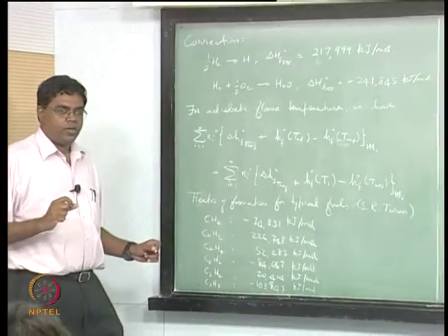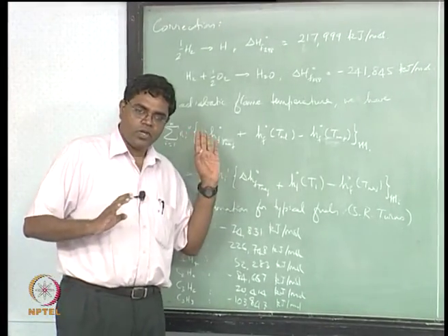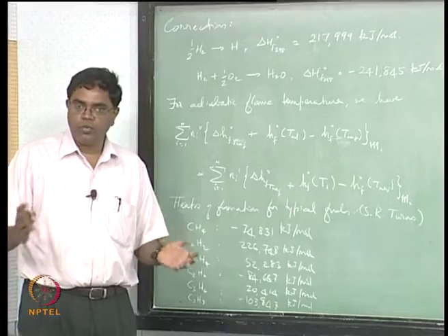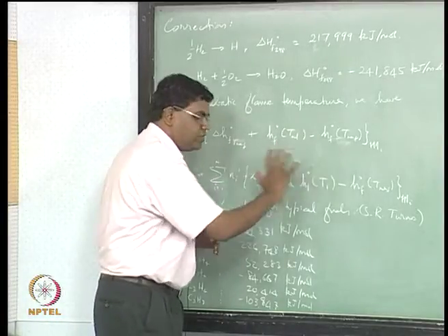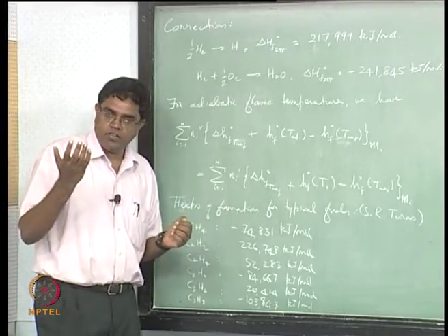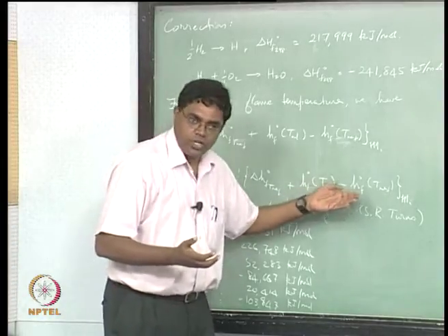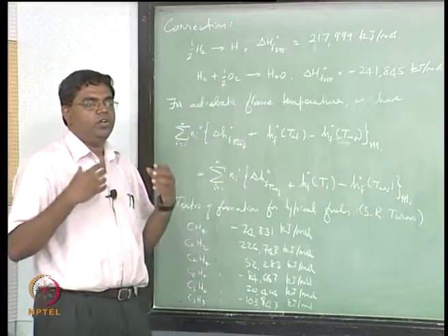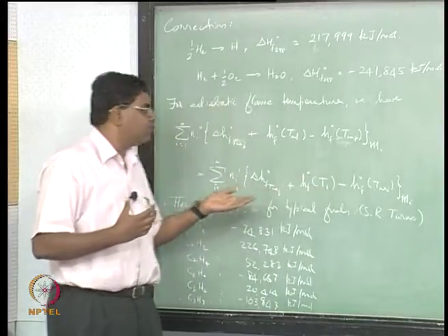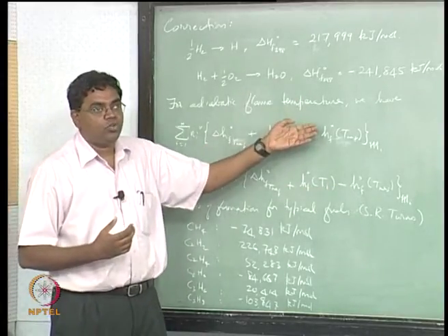So what we are looking for is, just for the sake of approximate argument, if you didn't bother about the fact that the reactants and the products had different CPs or molecular weights and so on, you're just simply looking at sensible enthalpies. I had a bunch of reactants at, let's say, room temperature or initial temperature T1, and that means the sensible enthalpy of that was pretty low, and I had to have this fuel release heat that will increase the sensible enthalpy of what were reactants to start with to a very high sensible enthalpy value for the products.